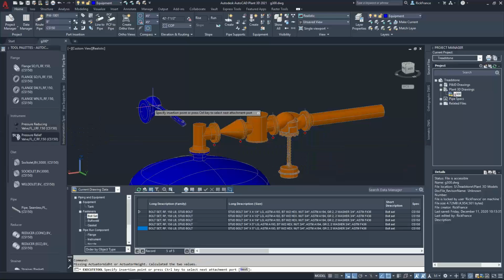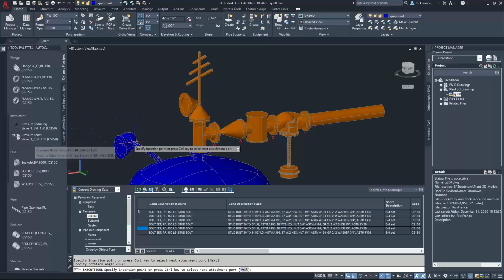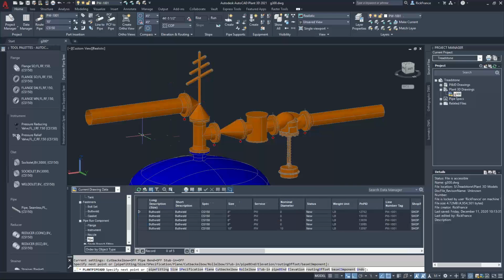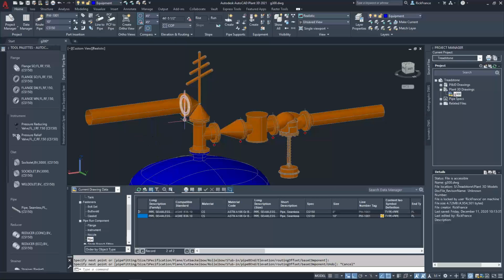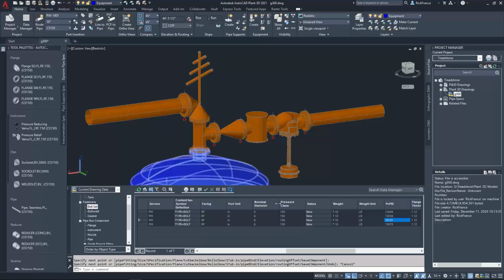And then we'll do the pressure relief over here, which will be flange to FLC. We'll go ahead and add the 10-inch line here, which I normally wouldn't, but it's just to be able to show the bolt sets, what happens on that one, because remember we did do a 7/8 inch one for that side, particular type.